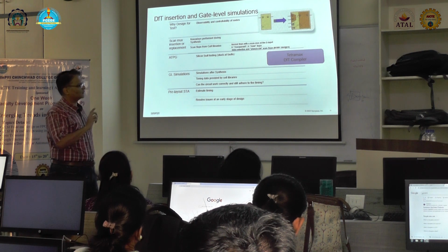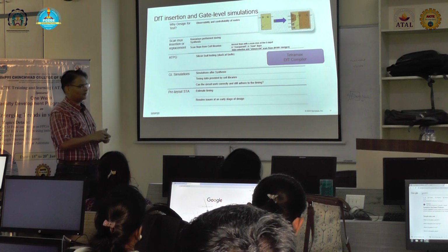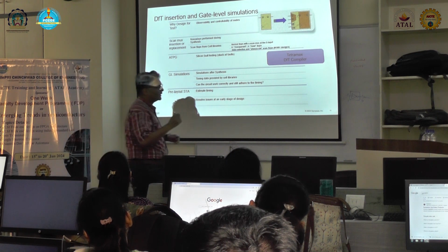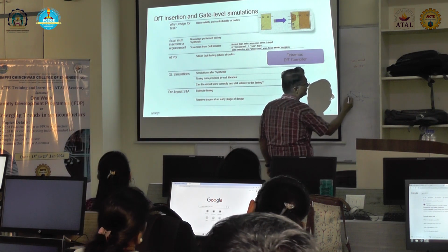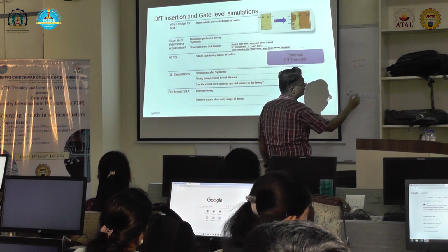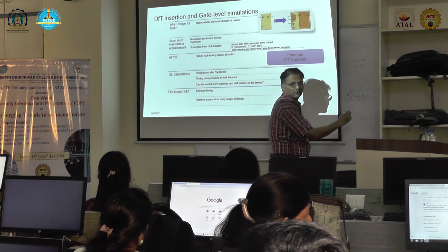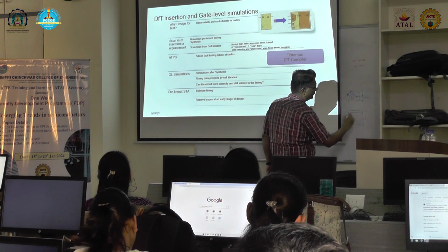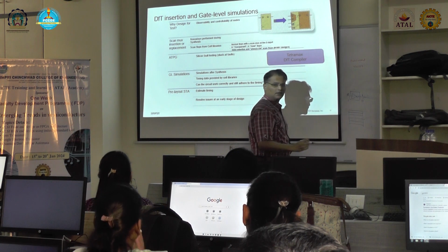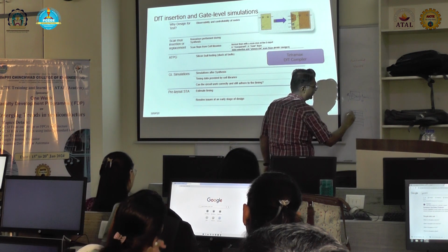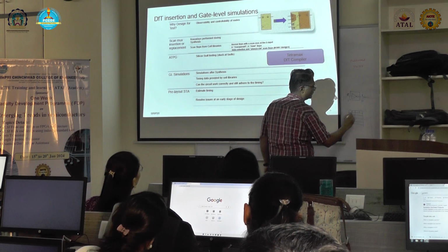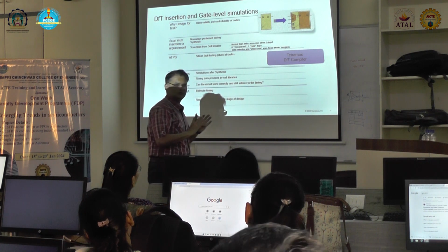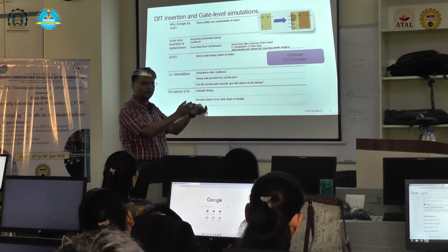So see, there is boundary scan. We generate the vector at our end. The design house, doing the boundary scan, means working out what the input is and what the output is. This truth table is stored in a file format. That is, when I input 0, I output 1, and when I input 1, the output is 0. So I store it in a file format, and this file I provide to them.